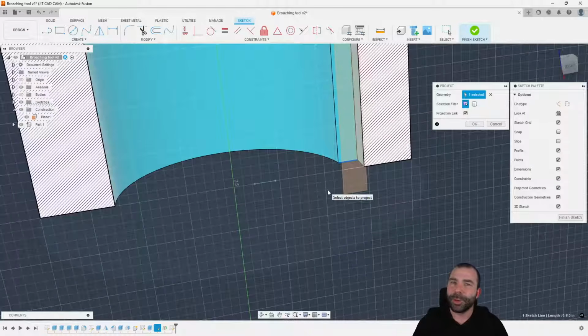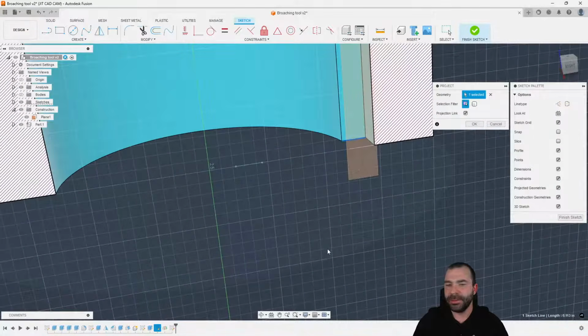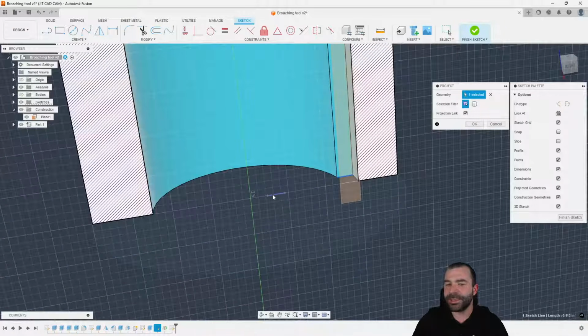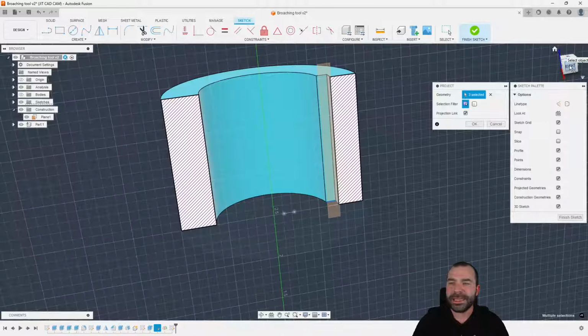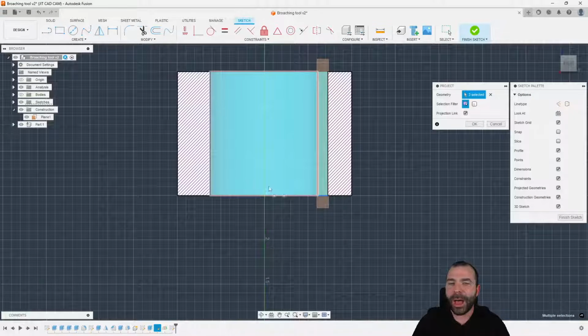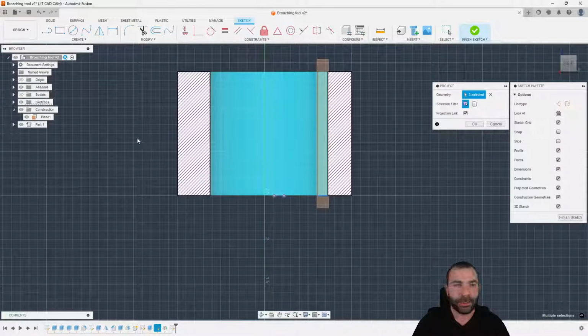So now, thinking more like a blind kind of broach, I have a bottom height here. Again, I know my distances from center. We have this other sketch. How you determine that, we could create a brand new sketch on this plane or this edge. Again, this is the distance from the center line of your tool to the tip of the cutting edge, but I can now draw how I want my toolpath to interact, right?